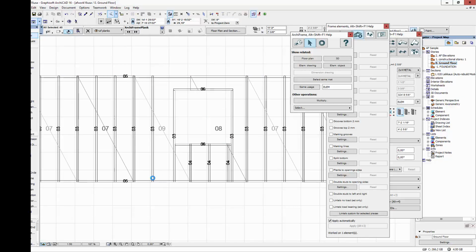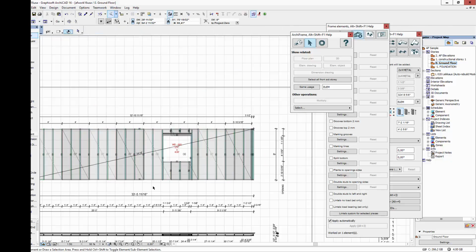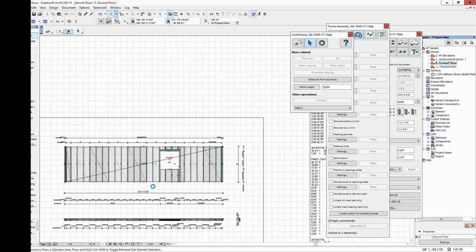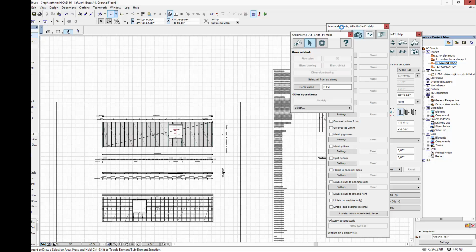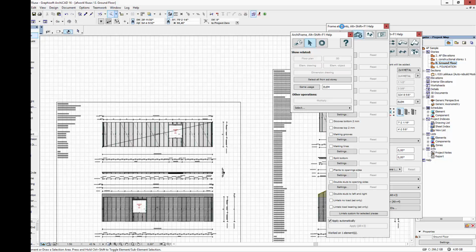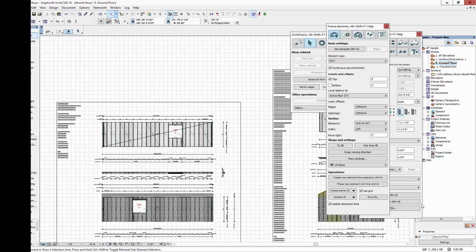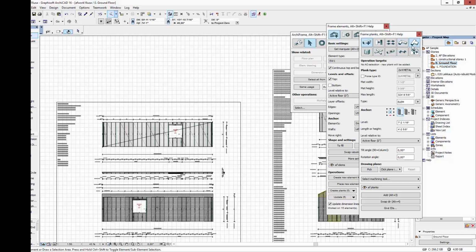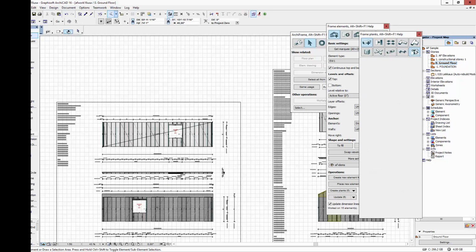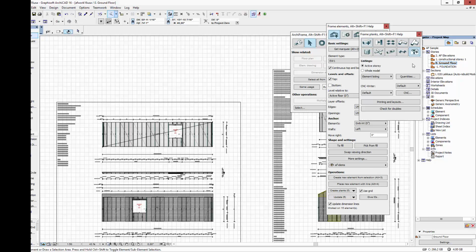When the elements are ready, you can produce the end results like listing and layouts. ArchiFrame doesn't maintain all the cut lists up to date all the time, but you need to manually update the elevations and cut lists before creating the end result. So to do that, I'll click the Update button. So after update, all the cut lists plus dimension lines are up to date, and we can go to the end results, which are here: the blank tools, CNC, Excel, and prints.